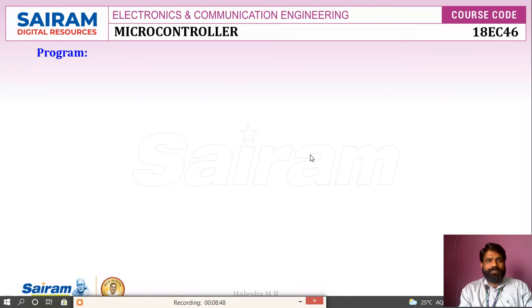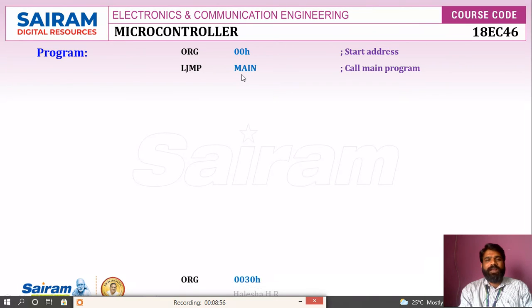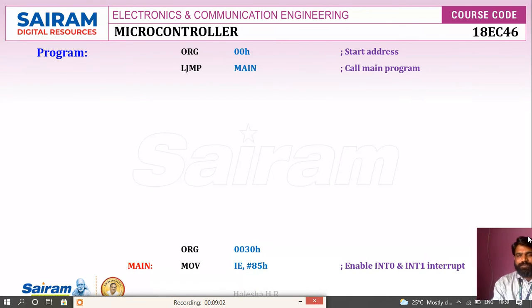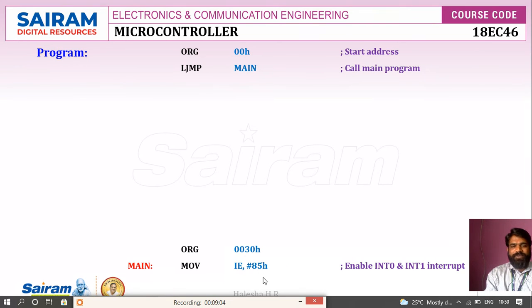Let's see the program. We'll start with ORG 00H and we redirect to the label main. Here in the main program, there is only one instruction, that is, we load 85H into the IE register to enable the INT0 and INT1 interrupts. Nothing else. Just wait for control to come back.